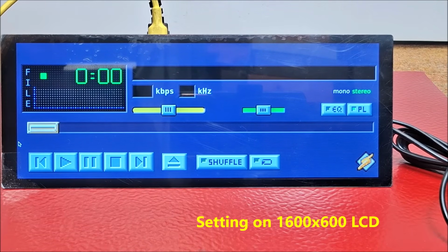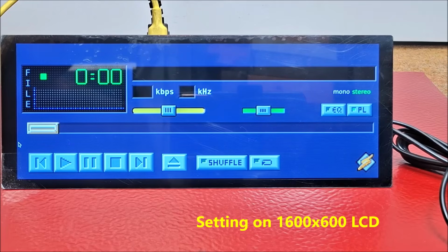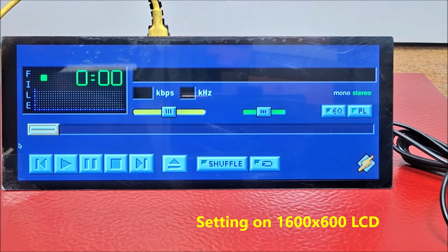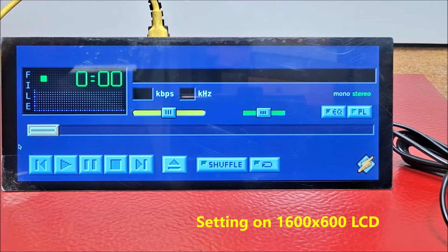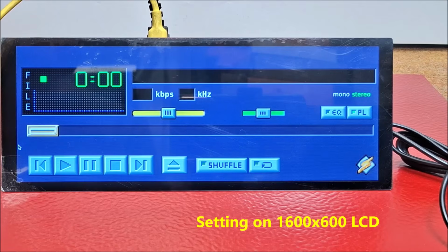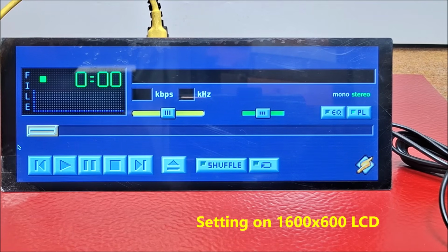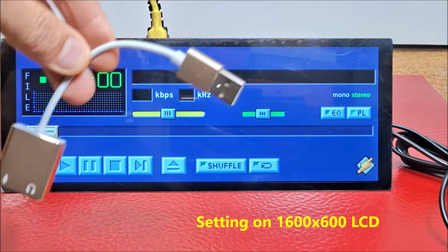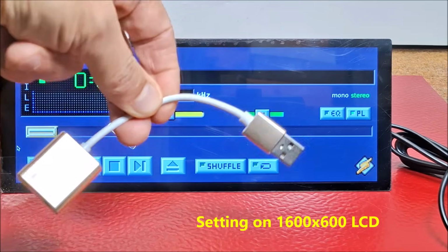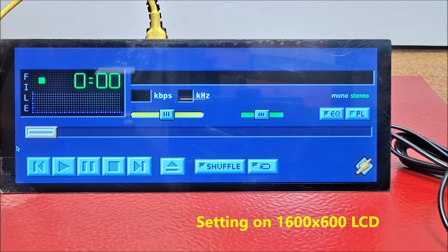One very important note: Raspberry Pi 5 does not have a standard audio port, but the sound goes through the HDMI protocol. This means in practice that this program will crash on startup unless there is a standard audio device. For this purpose, I installed this small cheap USB audio accessory. Actually, this is USB sound card.